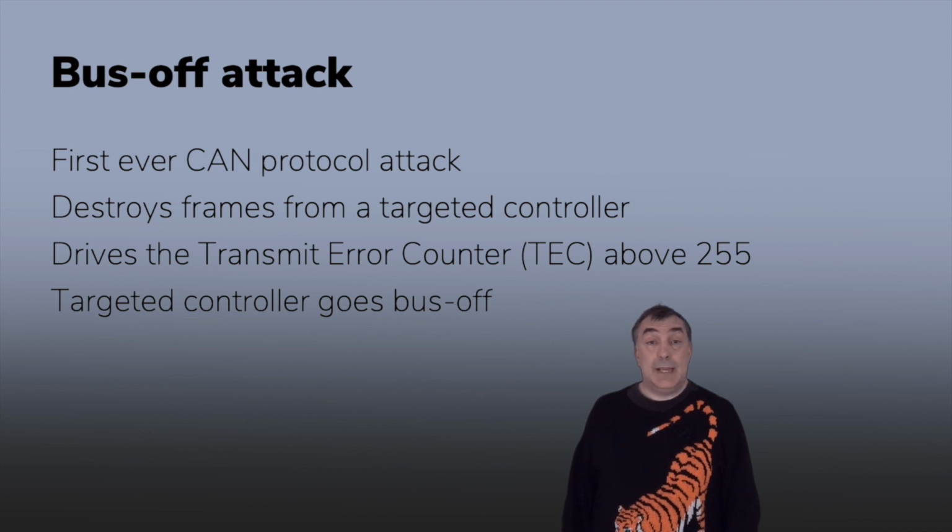When it's bus off, it cannot communicate, and recovery takes at least 3 milliseconds or up to 33 milliseconds on a busy bus. That's for a 500 kilobit per second bus. It's longer at slower bit rates. Let's go off to the lab and see the attack in practice.